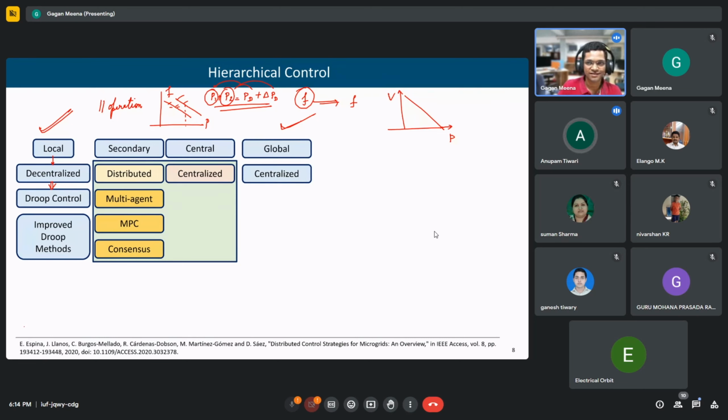In that case, in a DC microgrid also there is always a declining droop slope. Yes, droop is always like this. For AC it is a negative slope. But for DC also, what I want to ask is, why is it a negative slope? So you're saying it should be positive? No, it cannot be defined. I think it may be positive, it may be negative, but strictly negative should not be there. That is what I want to say.